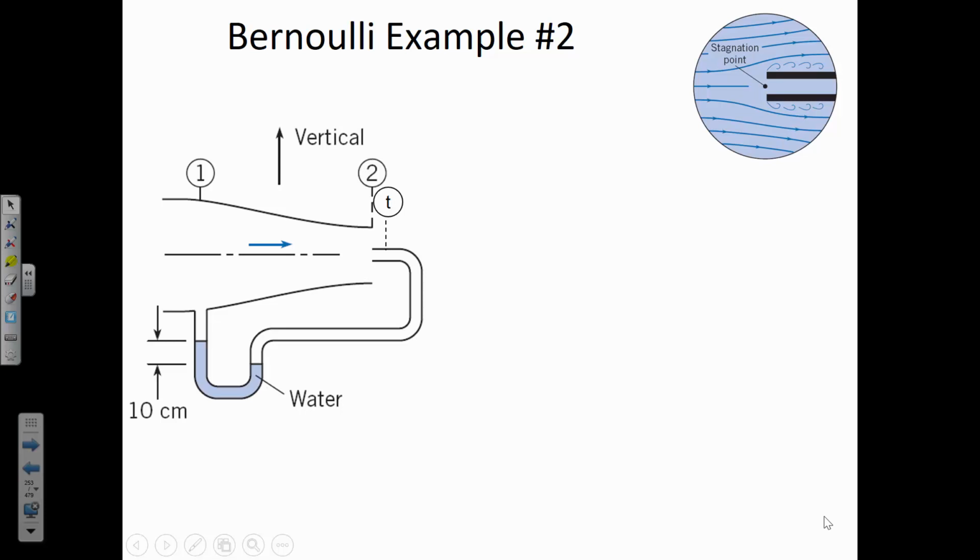But then what happens is that all of the energy that exists as velocity on the outside of that tube opening, as soon as that fluid encounters the tube where conditions are static, what existed as kinetic energy is instantly exchanged for potential energy. So there's an increase in pressure inside the opening of that manometer tube because the wind just dead ends. And so all of that energy has to go somewhere. It can't just be lost. It has to be exchanged.